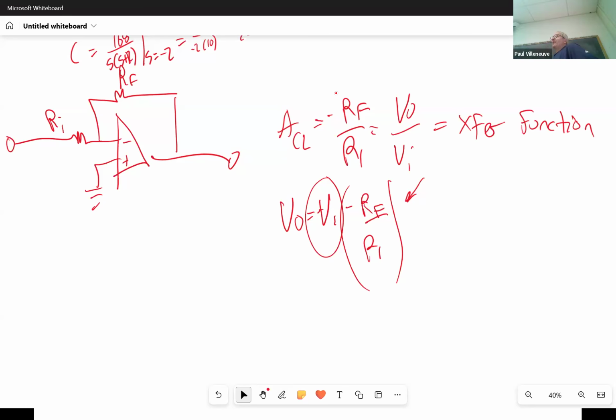So you can write a transfer function for anything. An input current to an output voltage, an input voltage to an output current. That's in electrical circuits. Can you think of anything else? In the process control industry, you can have a valve where the input can be a pneumatic signal, actual air going into a diaphragm that pushes or pulls on it, and that opens or closes the valve.